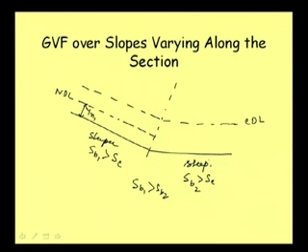This is steep. So in the second channel portion also, it will be less than critical depth, but this normal depth yn2 will be higher than the normal depth yn1, because this NDL2 will be higher than the NDL1, because this is steeper and this is comparatively flatter. The second portion is comparatively flatter than the first one.